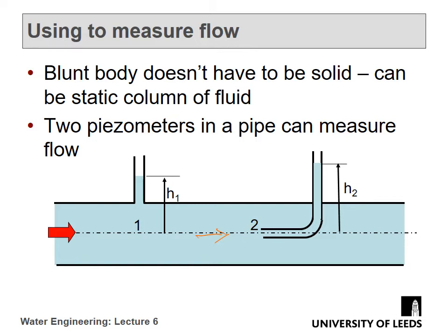Okay, remember this. So this height here we'll call the velocity head. It's rising up to this point because it's being pushed by the velocity of the fluid. Now this pitot tube here is just giving us a pressure that is equal to, well, the H comes from P equals rho g h, P over rho g.